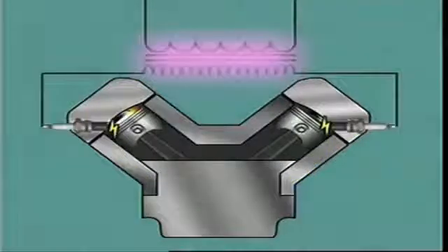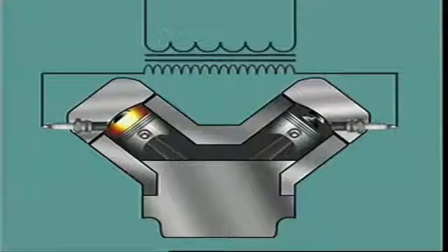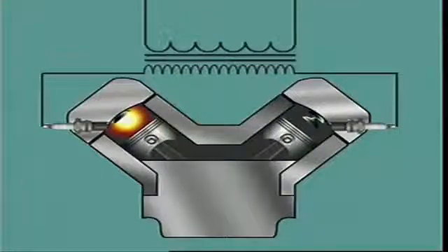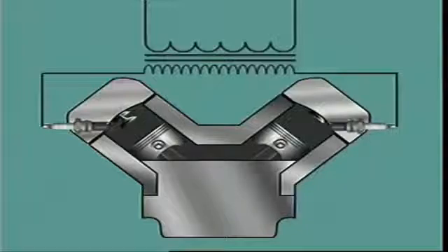The cylinder on the compression stroke with its charge of fuel and air is fired by its spark, driving the piston down on the power stroke, while the spark plug of the cylinder on exhaust simply serves to complete the circuit and is wasted.